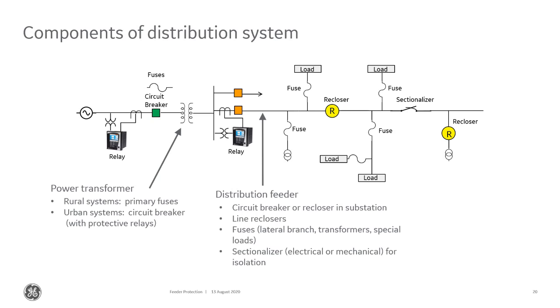So it might step down, for example, transmission voltage of 345 kV to 13 kV. Most of what I've dealt with, it's usually 138, 69 kV down to 13.4 kV, 33 kV, that kind of range. Then we have the distribution bus, and distribution, as the word suggests, distributes that power to various components in our power system, various loads in our power system.